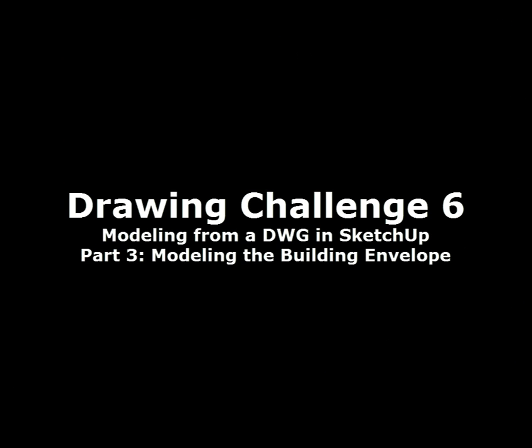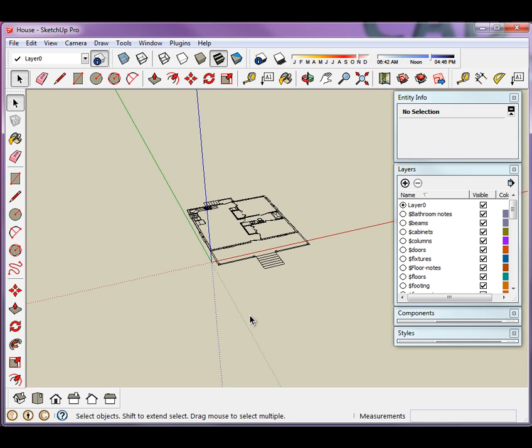Alright, in this video we're going to take a look at starting our cottage floor plan model, and we're going to start with the main floor of the floor plan. We'll come back and work on the porches, the front and the back porches, at another time. So to begin, let's make sure we're still in layer 0.